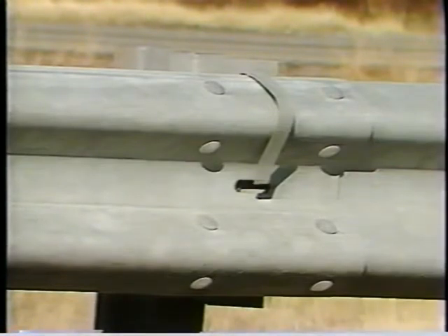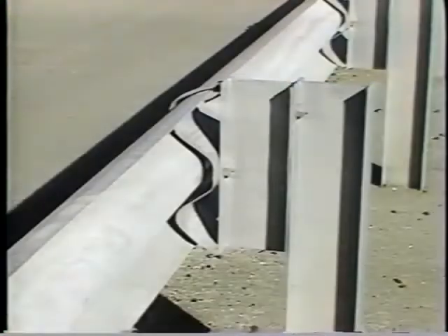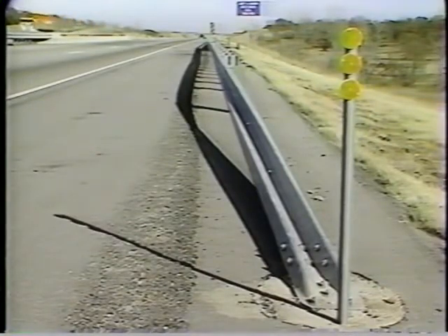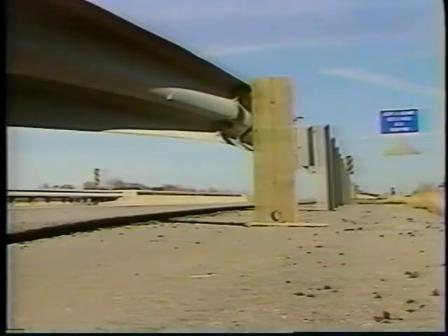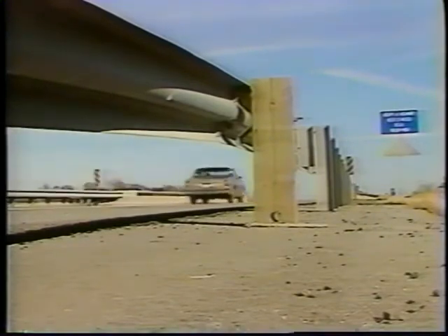Various rail post connections are used. To set up the system, a short section of W-beam is bolted to the posts. The barrier railing is then placed into this section and rigged to be held there by a weak galvanized steel clip over the top rib of the rail. Any significant downward load on the railing, such as the weight of a car, pushes the rail down from this connector and allows the W-beam to fall harmlessly to the ground. The impacting vehicle then either continues on to shear off weakened posts or until it decelerates to a stop in a runout area behind the rail end treatment.